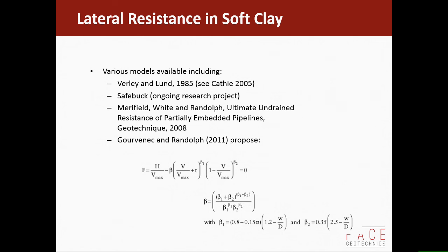And what that does is generate, if you think of the clay as this soggy, wet collection, a bit like a sponge, but water doesn't run through it very easily. You sort of squeeze it a little bit and some water slowly runs out, okay? As that water runs out, you get more to a drained response, and the interface becomes more like a frictional type response.